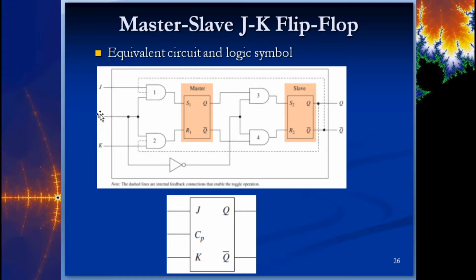So the clock pulse comes into the first set of these AND gates here. And while CP is high, remember we talked about enabling and disabling signals in 112. So we're enabling, right, when you've got AND gates that are acting like an actual gate out here, and you have a high on one of those inputs, it enables the other two. So if you have a 1, 1 here, those ones get passed on to the SR, okay?